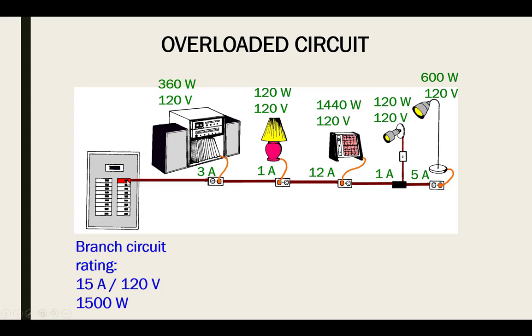Why is that? Because this wiring that's been run was designed for 15 amps. And if I put a breaker in here that will handle 20 amps and the wire will only handle 15 before it starts to heat up, melt the insulation, start a fire, then we have a problem.